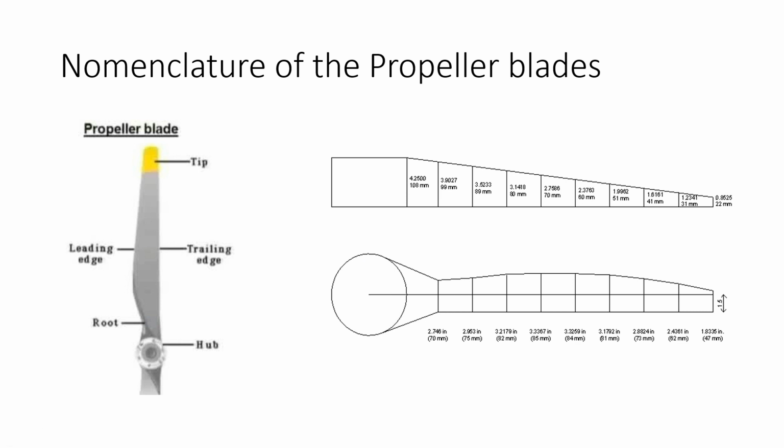By the thrust equation we know that thrust is equal to mass flow rate times the difference of velocity at the exit minus the velocity at inlet. So the propeller is basically accelerating a mass flow rate through a differential velocity. You have some mass flow rate, the propeller is simply increasing the velocity of it and moving it to obtain thrust. That is the basic idea behind the propeller.